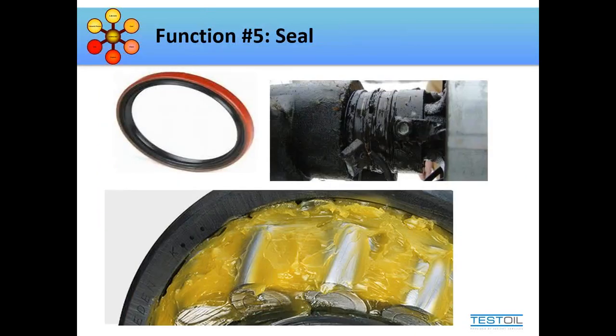It also provides seal capabilities. In particular, this slide here shows grease packing. And the grease is a good way to keep particles out between, say, a seal and the outside elements. You can pack it with grease, or sometimes you've got oil layers in there that can actually keep the particles and the dirt and stuff out.